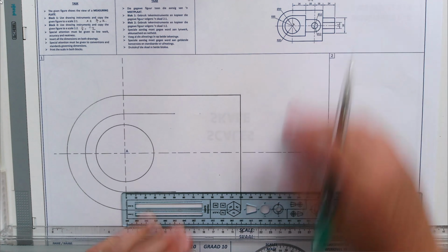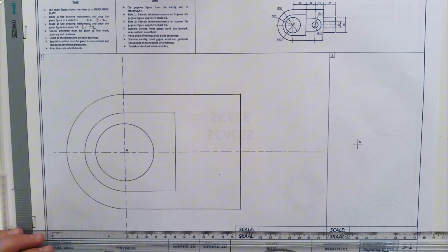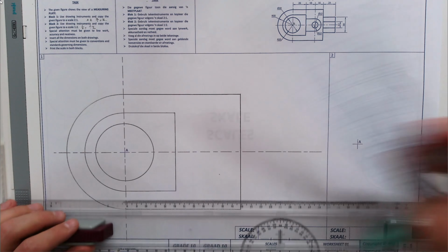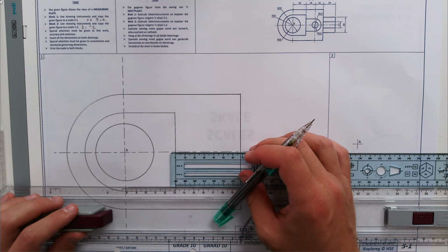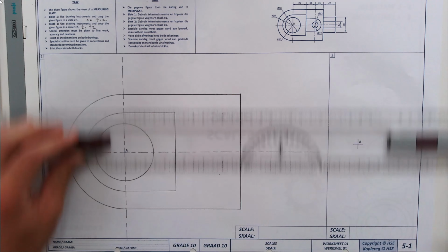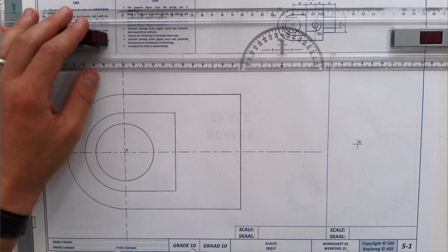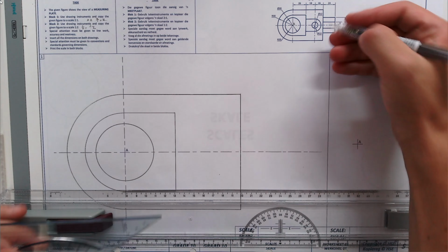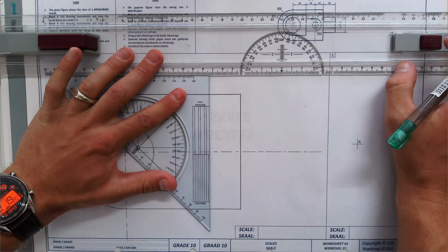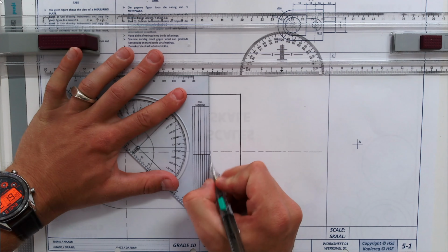Now we still need to add this in and this at the back. Now to get to this center point, we need to go 18 to the right. 18 times 2 is going to be 36. So from there we need to go 36. Make a mark. There our center point will be. I'm going to draw a vertical center line. You can see that the center line goes through the whole height over there. So let's put that center line in. Short, long, short, long.